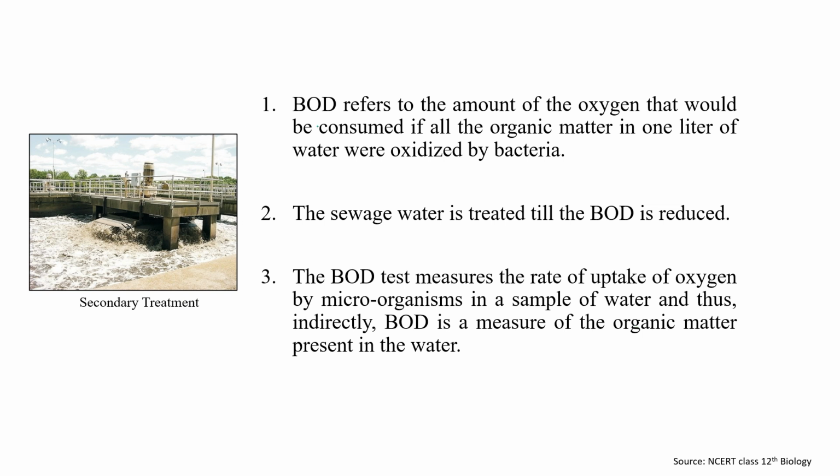So what is BOD? What is the definition of BOD? BOD refers to the amount of oxygen that would be consumed if all the organic matter in 1 liter of water were oxidized by bacteria, the maximum amount of oxygen that would be consumed by the bacteria.